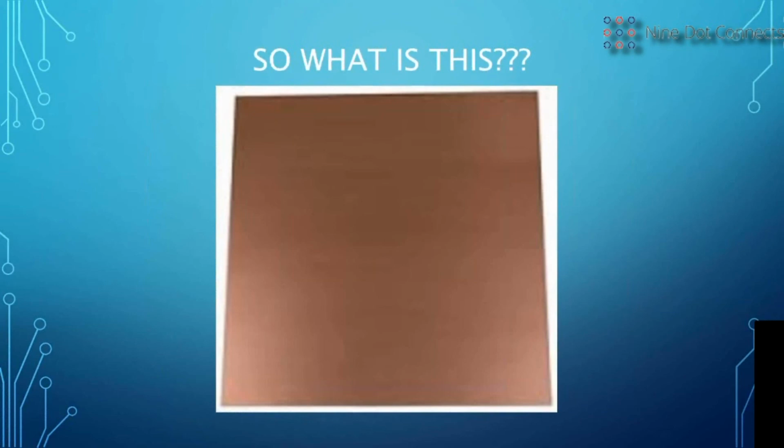Well, what I see is a fat half-wave dipole antenna. It's just a little wider than a piece of wire. The charge can accumulate on the left edge or on the right edge, and it can slosh back and forth between the two with currents flowing. And as it flows, it's going to create a magnetic field. As it starts to flow and the charges equalize, the collapse of the magnetic field will drive it the other direction. So it continues to slosh back and forth.